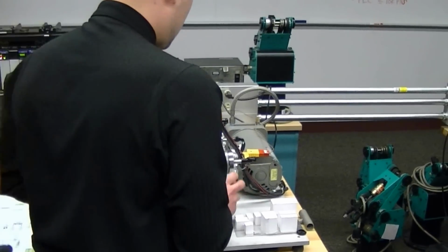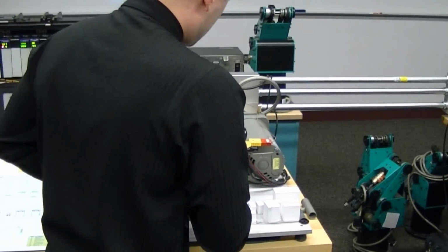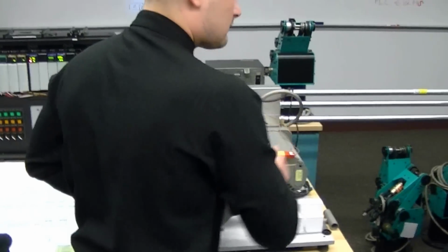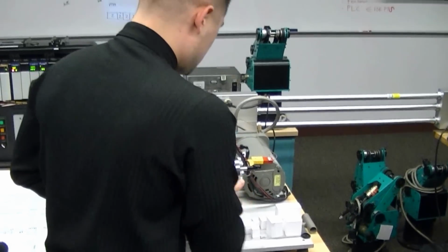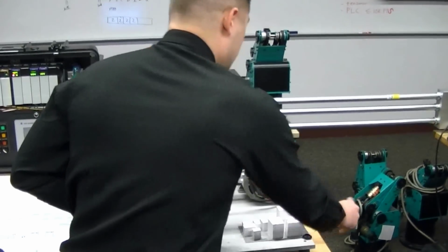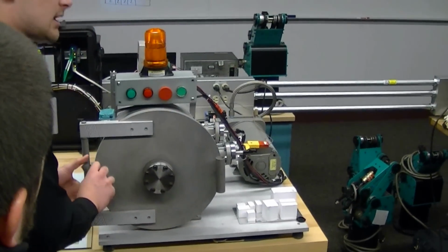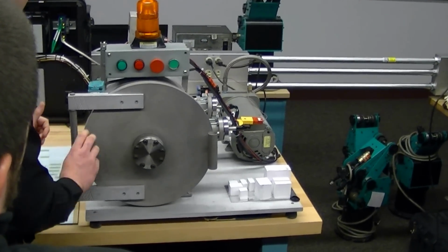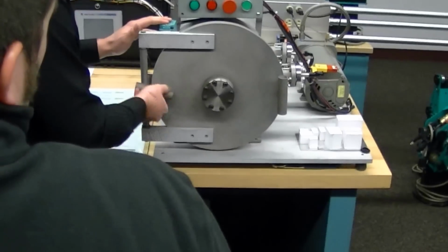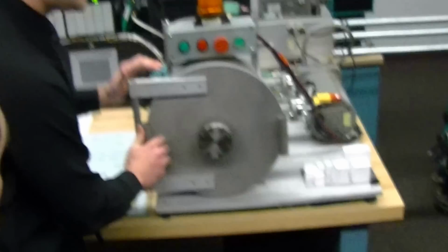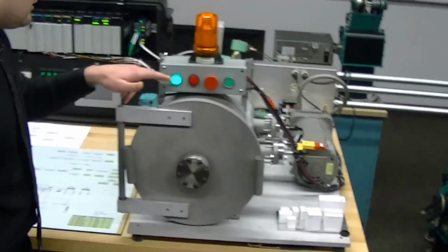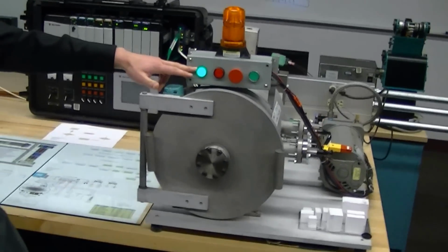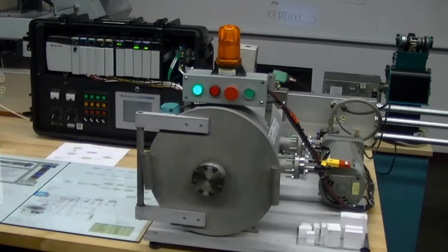This is atmospherically sealed with a Viton O-ring to prevent air leaks. The thermocouples and the electrical feed-throughs are isolated with Teflon, so there's no atmospheric leaks and electrical isolation for safety. And once this is sealed, the safety requirements as far as the door limit switch are applied, and then the user has to manually engage the system with a green push button, and you have an indicator light saying that the system is in ready mode.